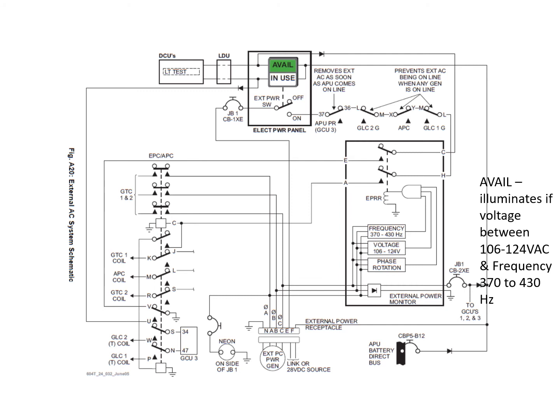Now if we just go down to look at where the external power plug is, you'll see there's a pin F, and there's a line coming up. Actually, the line looks like it's coming up between E and F. If you follow that line up, it goes to a circuit breaker and up to the external power switch. So to put external power on, you obviously have to switch it on. So the switch has to be in the on position.